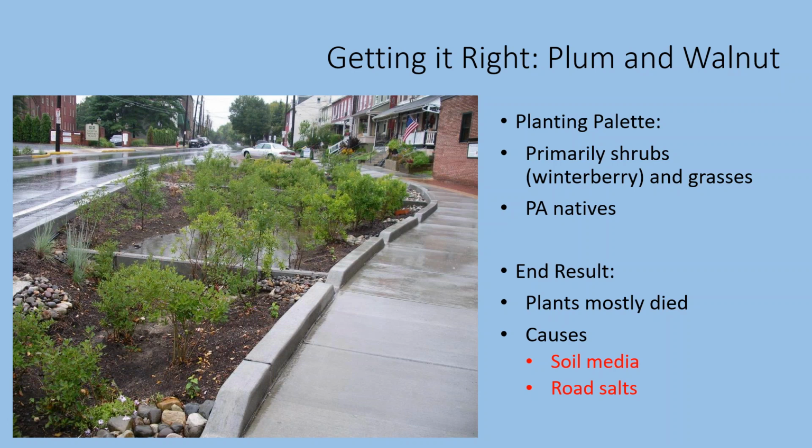At the end of this first growing season, almost all of the plants in these facilities had died. And we did track that back to the fact that the soils were not appropriate for the plants that were placed in there. And they were heavily influenced by road salt, so the pHs were a little off in terms of those plants. Next slide.